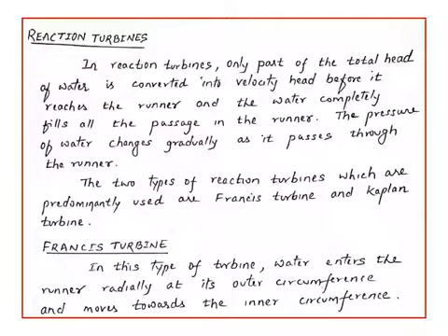I had already discussed the Kaplan turbine in my previous lectures. So today I will be concentrating only on the Francis turbine. In the Francis turbine, the water enters the runner radially at its outer circumference and moves towards the inner circumference.